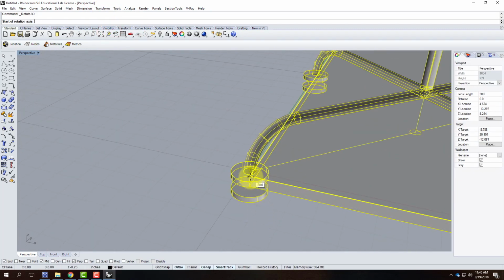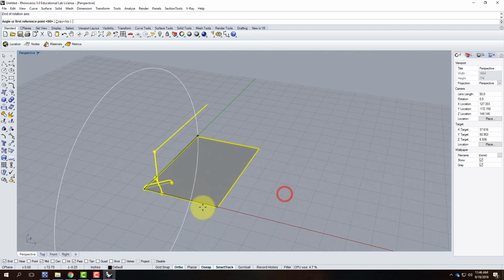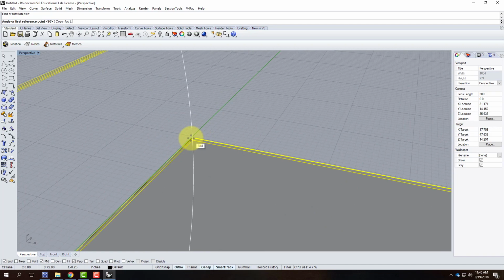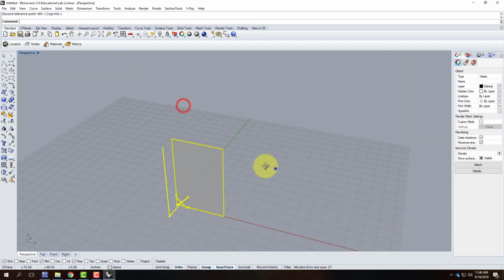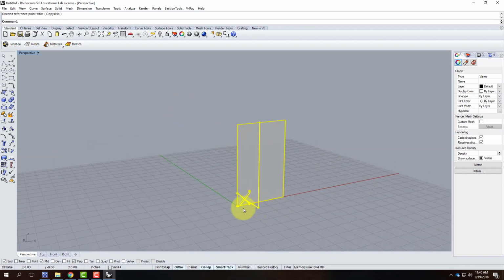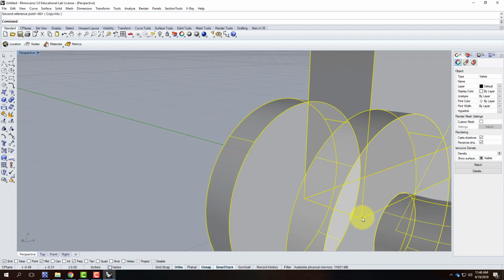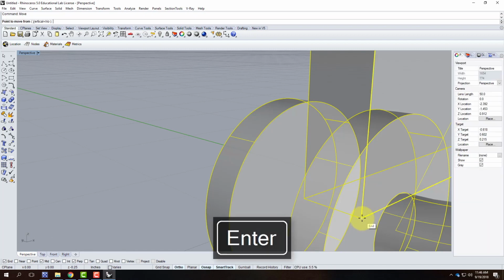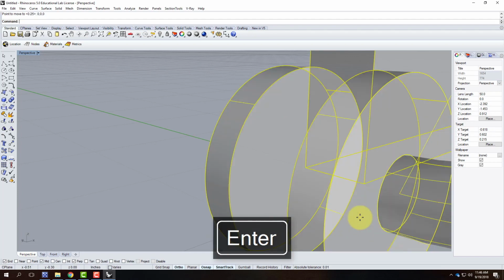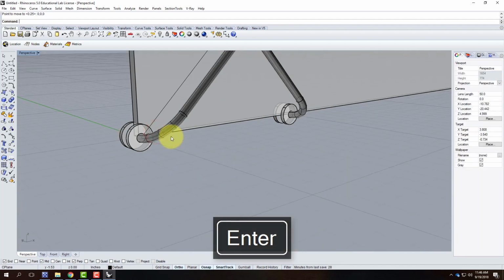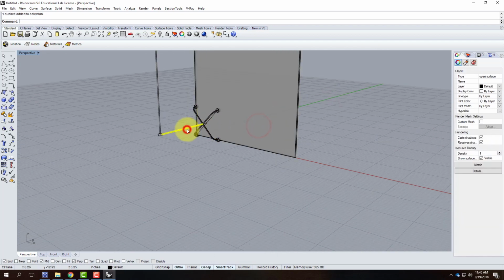And we'll start with my sheet of glass. And we'll go across the sheet of glass. We'll go up vertically on the sheet of glass. And then we'll stand it up so that it's actually standing up like that. For cleanliness purposes, I'm also going to move the glass to be at 0, 0, 0. So that point of the glass will be at 0, 0, 0. And I'll hit enter. It just moves it up ever so slightly. And that gives me the glass with the clamp.